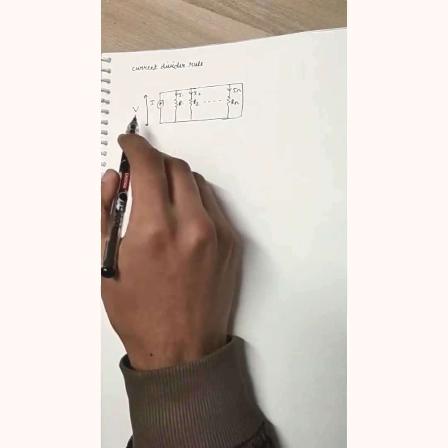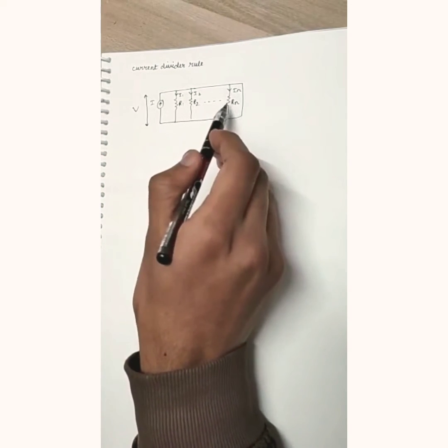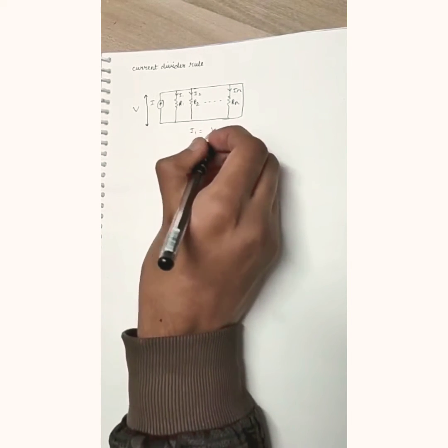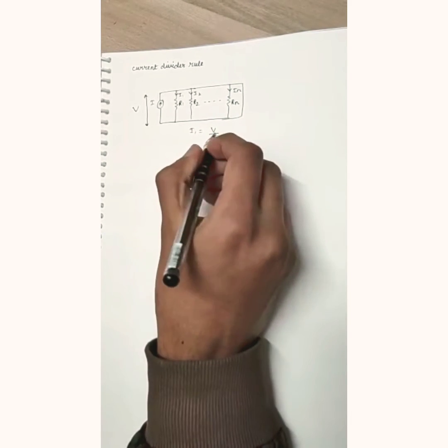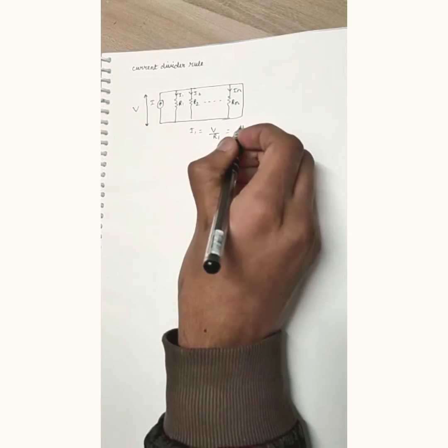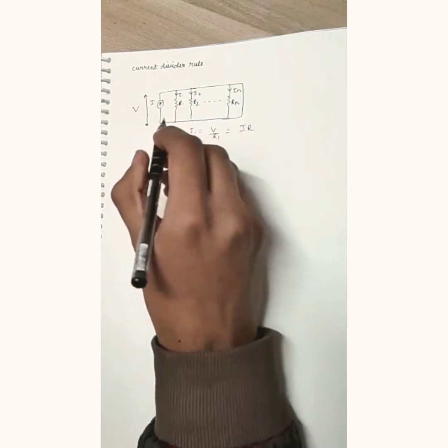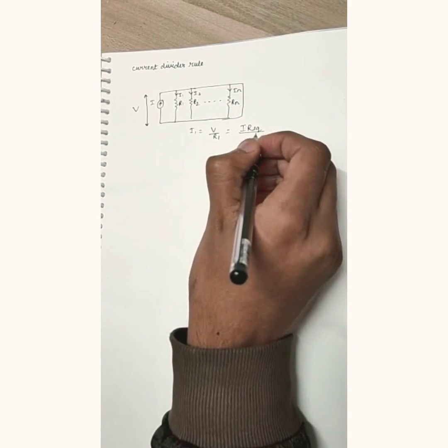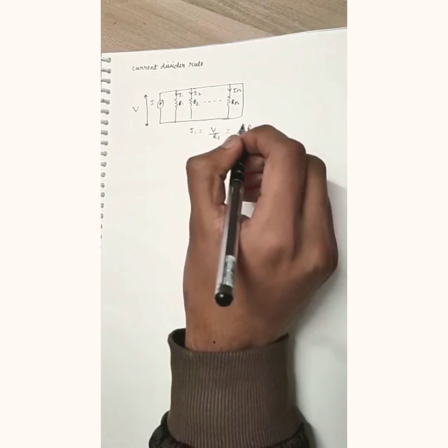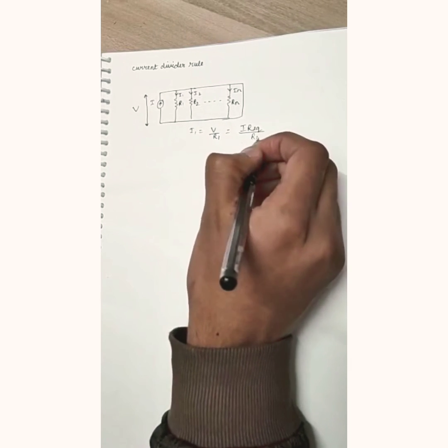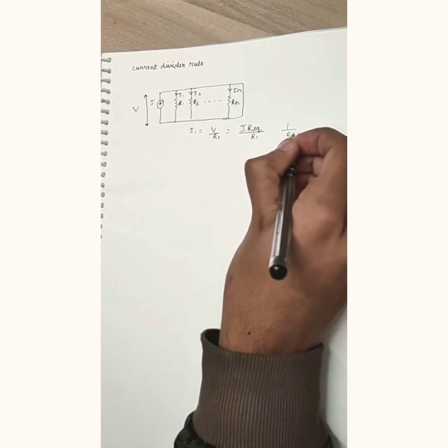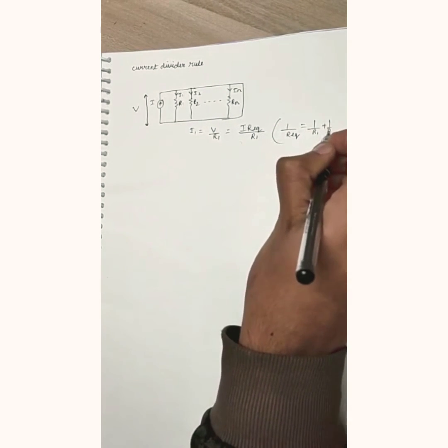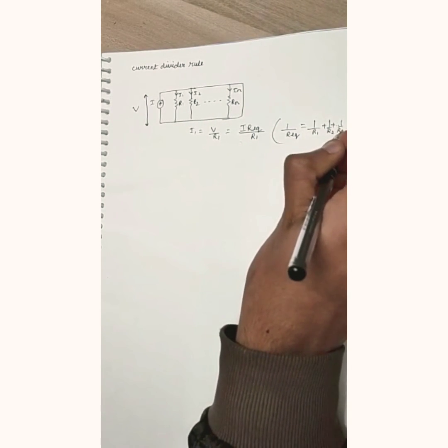The same will be the voltage difference across every resistor in this particular circuit. So I1 you can write from Ohm's law as V divided by R1, and V you can write from Ohm's law as V equals IR. In our particular case it will be I into R equivalent, where R equivalent is the net resistance of this circuit, divided by R1. You can find R equivalent from this formula: 1 upon R equivalent equals 1 upon R1 plus 1 upon R2, and so on up to 1 upon Rn.